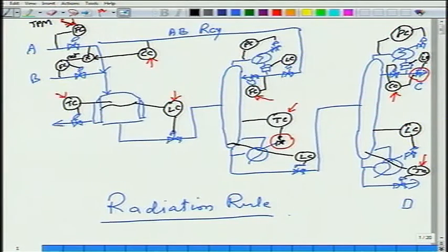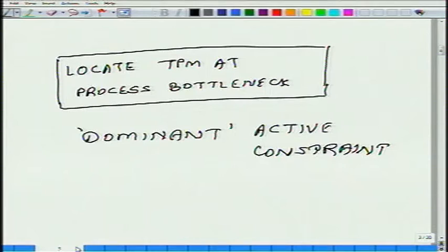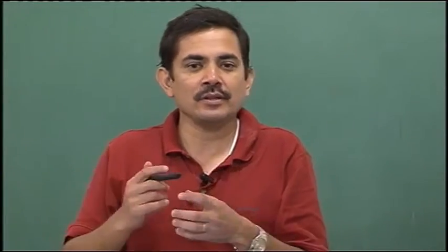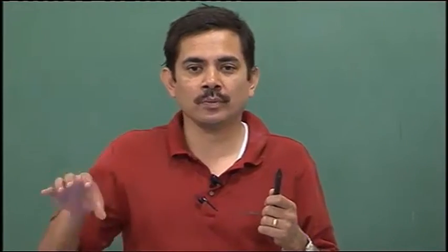If you look at the other two control systems that we drew, for on-demand production or with boil-up in the second column as my throughput manipulator, even in that case, the way I put in the loops, it was ensuring that quality is maintained no matter what. Does that make sense or no? Does that answer your question? Okay. So yeah, that is a good point, in the sense that quality must always be controlled tightly. You put in those loops, and even then you still have the flexibility of where you want to locate the throughput manipulator.